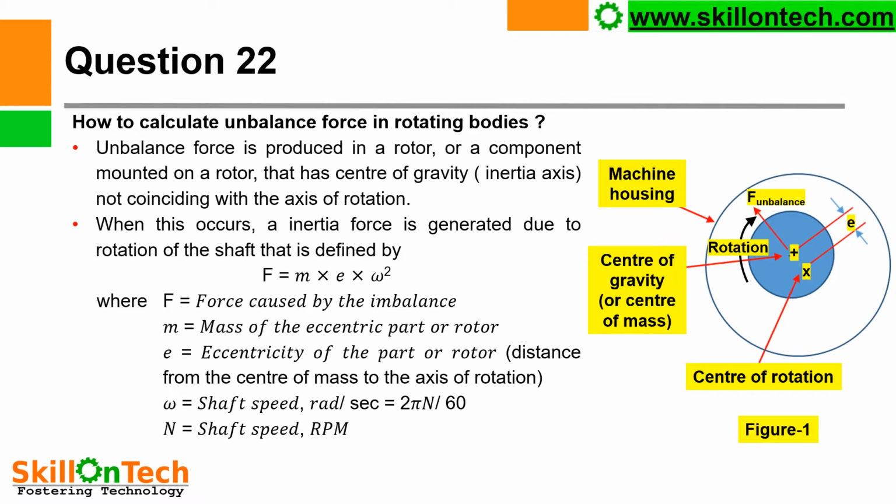How to calculate unbalanced force in rotating bodies? You can see a picture where a center of rotation is shown and a center of gravity, center of mass, is shown differently. You can see an unbalanced force F and a perpendicular distance E between the center of rotation and the center of mass, that is called eccentricity.